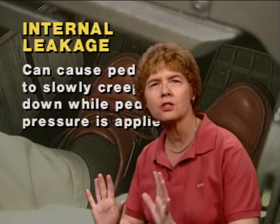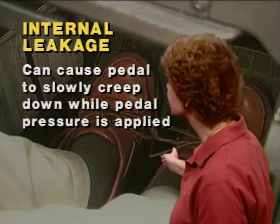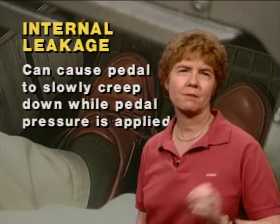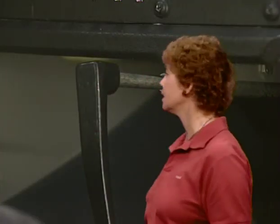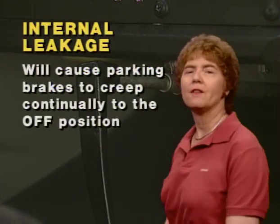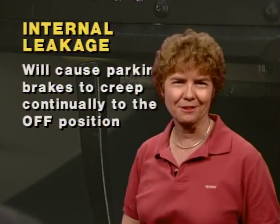But the pedal slowly creeping down while you've got the pedal pressure on is probably the result of internal leakage in that brake master cylinder unit. An internal leak like that will also cause the parking brakes to continually creep to the off position. They just simply aren't holding the pressure because of that internal leak.